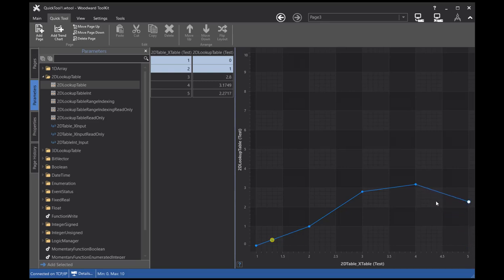To use the keyboard to edit the output array values, click on the data point to be edited. Edit the value by pressing the up or down arrow keys for coarse adjustment. Hold the Control key down while using the up or down arrow keys for fine adjustment. You can move the selection of the editing data point by using the left and right keys on the keyboard.